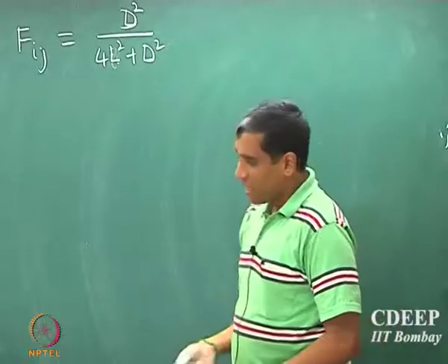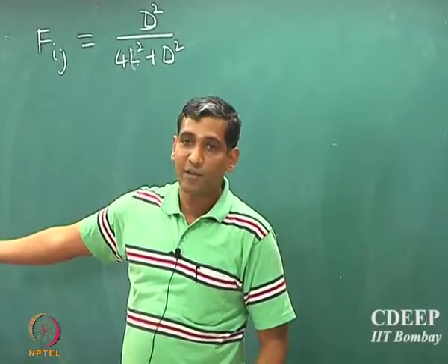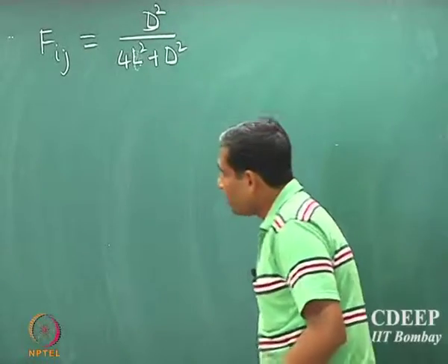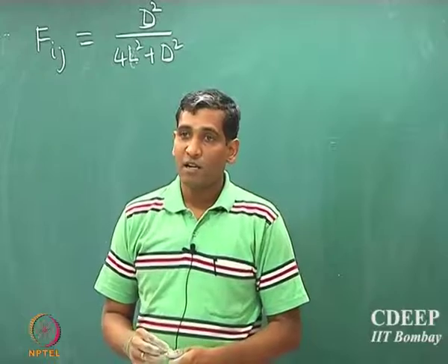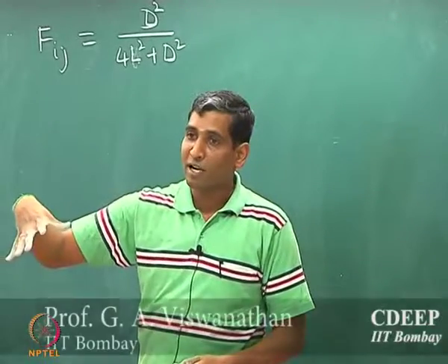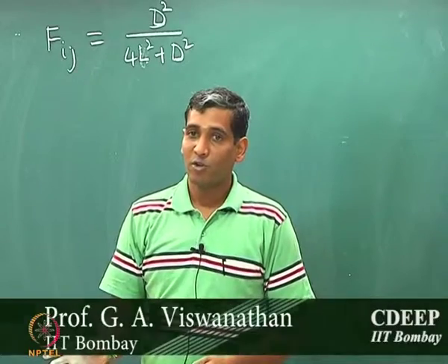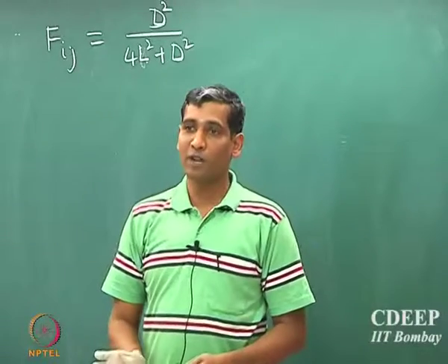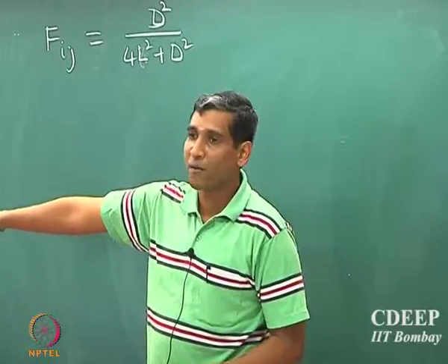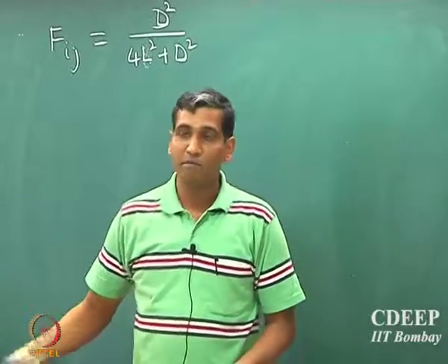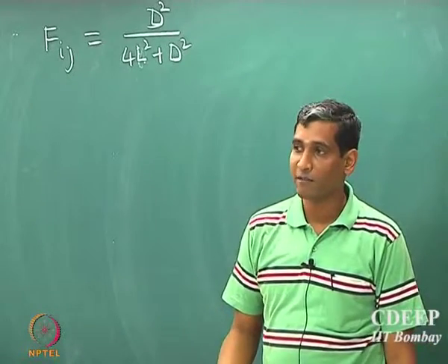So in this particular case, we have no option but to do the full integration. One important thing you have to keep in mind is, whenever you do this integration, the area that you are calculating and the solid angle involve 3 dimensions. So you have to be very careful how you construct the geometry. This is a very simple example where constructing the geometry is very easy, but there are many cases where constructing the geometry can be completely non-trivial.